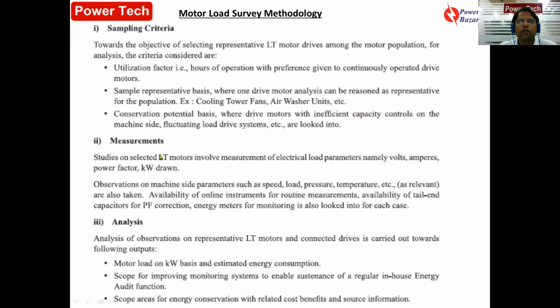Then after sampling, we need to go to the motor and do certain measurements. In the measurement, we have to calculate the voltage, current, power factor, and kilowatt, and you also need to understand the load side measurement. That means what is the flow and pressure if it is a pump, what is the temperature, what is the speed of the motor, and what is the load size. Based on this, we can calculate the loading of the motor.